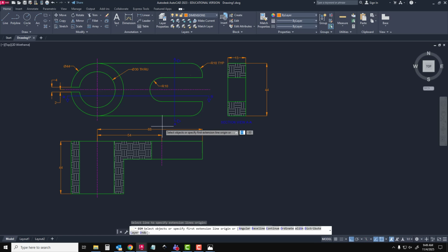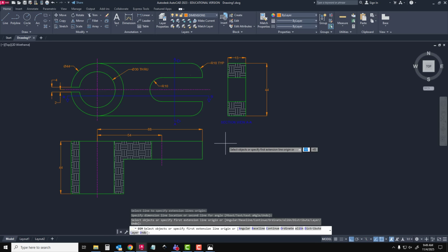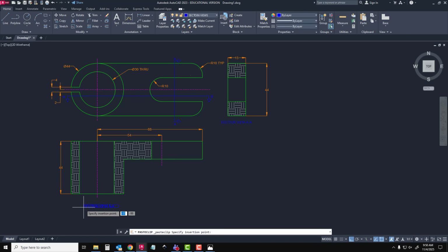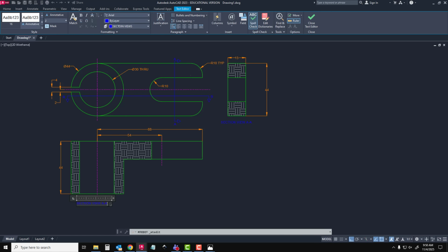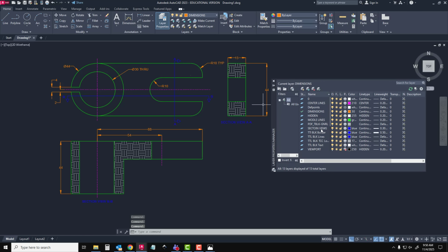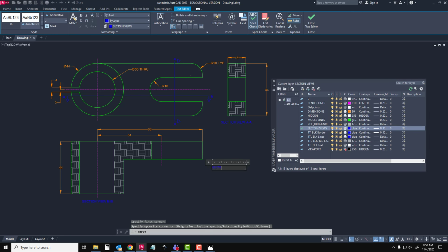And the good news about using this print as a tutorial is there's not a lot to dimensions. So if I'm missing something, feel free to make the comment about it, no big deal. But all my hatch lines are there, all my model lines are here. I do need to put the section view, so I'm going to go copy, Control V, double click on it. This is section view BB. So let's click off it, and like I said, don't make things too hard on yourself, make it easy. And I need to put the word metric down here. So I'm going to click on here, go back to section views, type on text, type in the word metric.